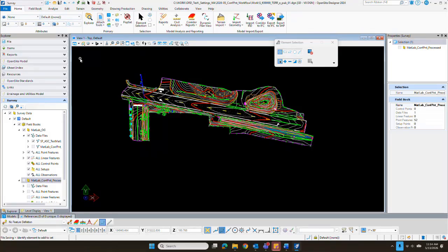We need to go back out. You may take some additional confidence points. You're going to take confidence points today so that you can see that the ground today is still what it was 3 years ago, 2.5 years ago, whenever it was we started the terrain file. And this is somebody else's work. You don't want to mess with somebody else's terrain file.